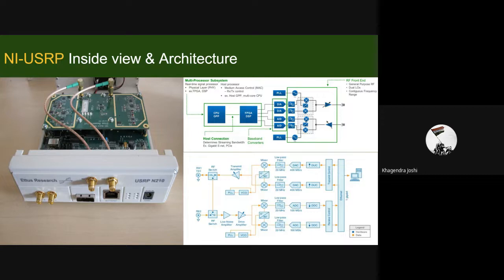So this is what is followed: baseband signal up converted, converted to analog, low pass filter, passed through the mixer, amplified, and transmitted. Now the second USRP receives: low noise amplifier, mixer, right? Then analog is converted into digital, then down converted, and after this we have the baseband signal, which we can see via the Ethernet cable. It gets fed to the LabVIEW platform, and there we can see that particular signal. Right. So this is the internal circuitry of the NI USRP.